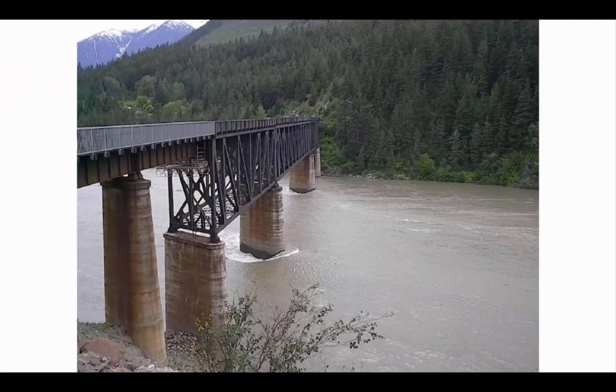All right, here is a picture of a bridge going over a river, and it looks like this is probably out west somewhere, just based on the mountains and the trees and all that. But the interesting thing is these piers that are in the river to help support the bridge are reducing the effective width of the channel. You've got a certain amount of water, a flow, Q, going through this river, but when you put the piers into the channel, at this location the river isn't as wide, because the water can't flow through the concrete, it has to flow around it.